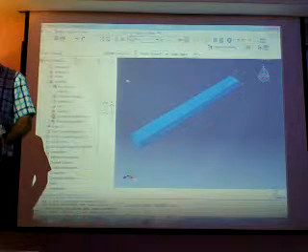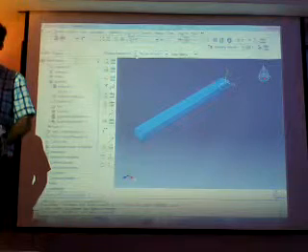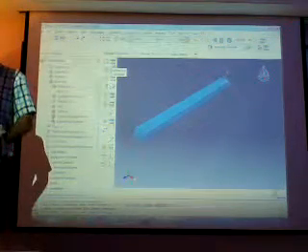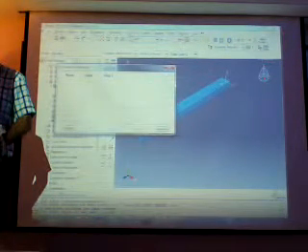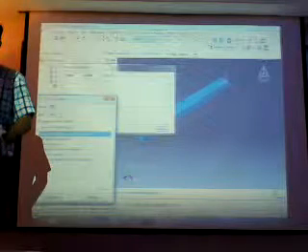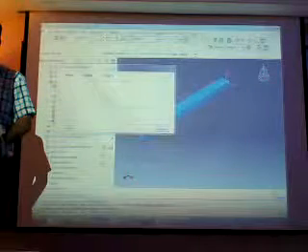After a step, we have interaction, because here just we have one part, we don't need for interactions. In interactions part for the multi-part models, you can create your interactions here, create, and we have different kind of interaction. Surface to surface, self-contact, model change, and other things.